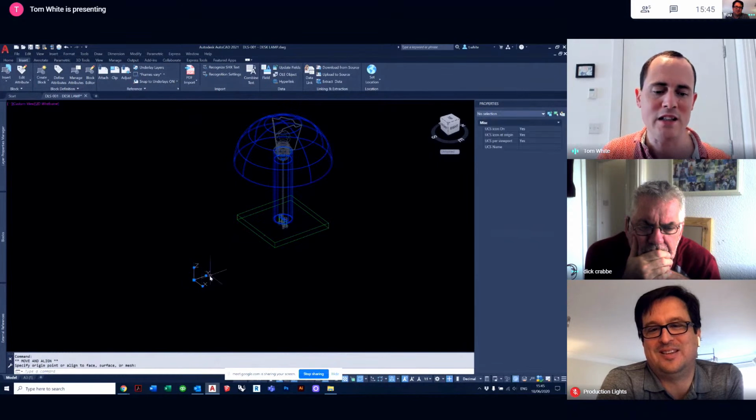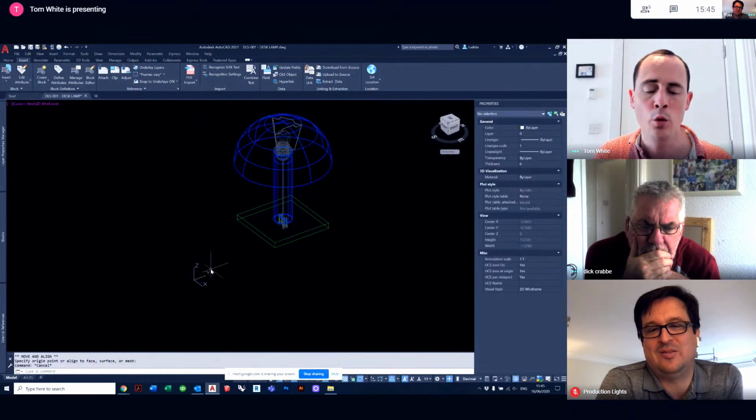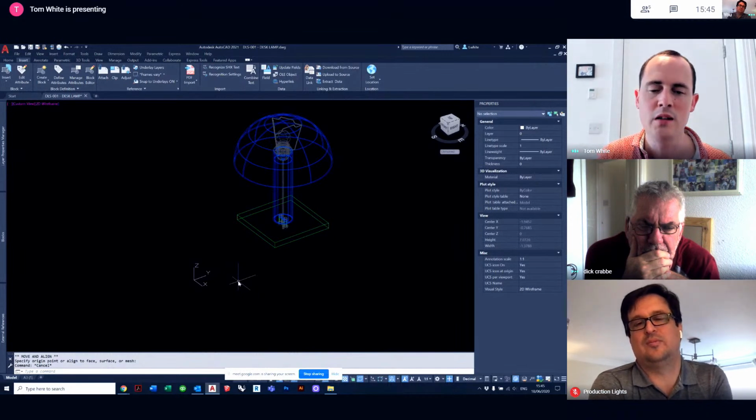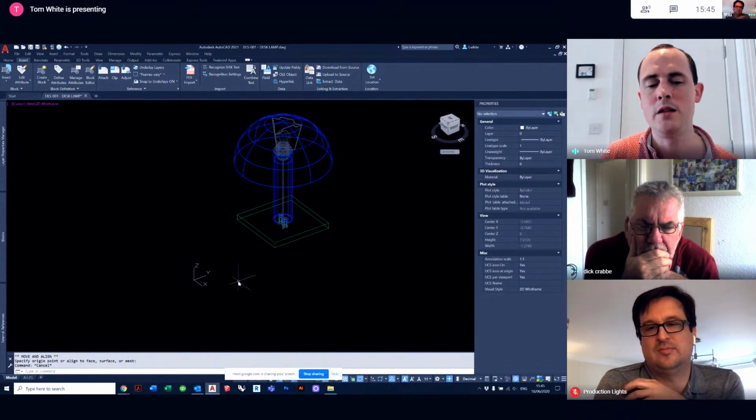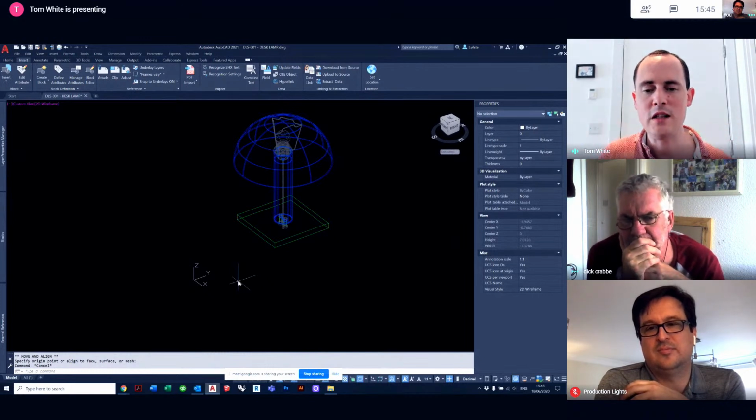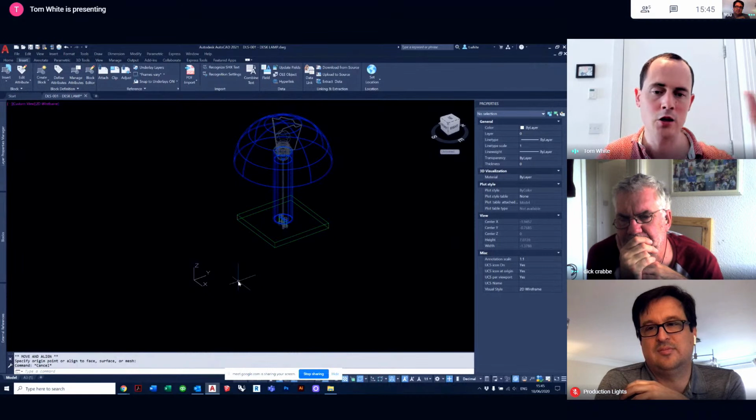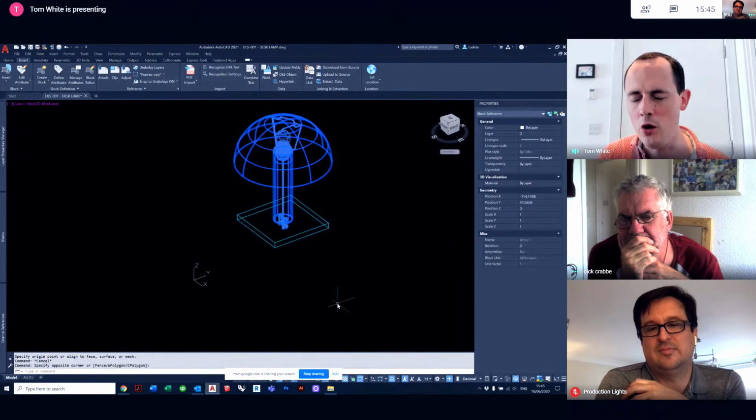So what you're doing essentially, I'm going to click escape, what you're doing essentially is editing the center of the drawing temporarily, but you're able to save the drawing, and I'm able to save it and send this to Dom, and Dom could open it. And at a glance, it seems like my lamp is not on 0, 0 of the drawing, because the UCS is not in its original location.